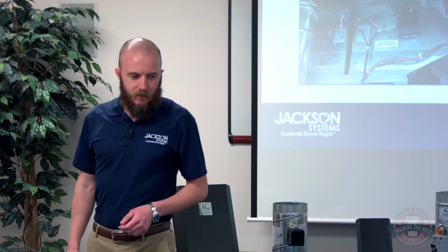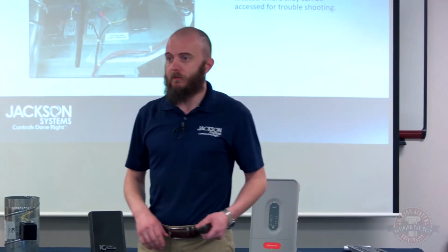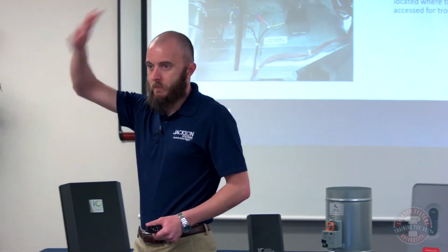So obviously you can't control what a homeowner is going to do after you leave, right? So you install a bunch of dampers in a basement and 6 months later they come through and finish the basement and bury all those dampers behind a bunch of drywall. There's nothing you can do about that after the fact, but whenever possible, put dampers where they're going to be able to be accessed for serviceability, troubleshooting in the future.